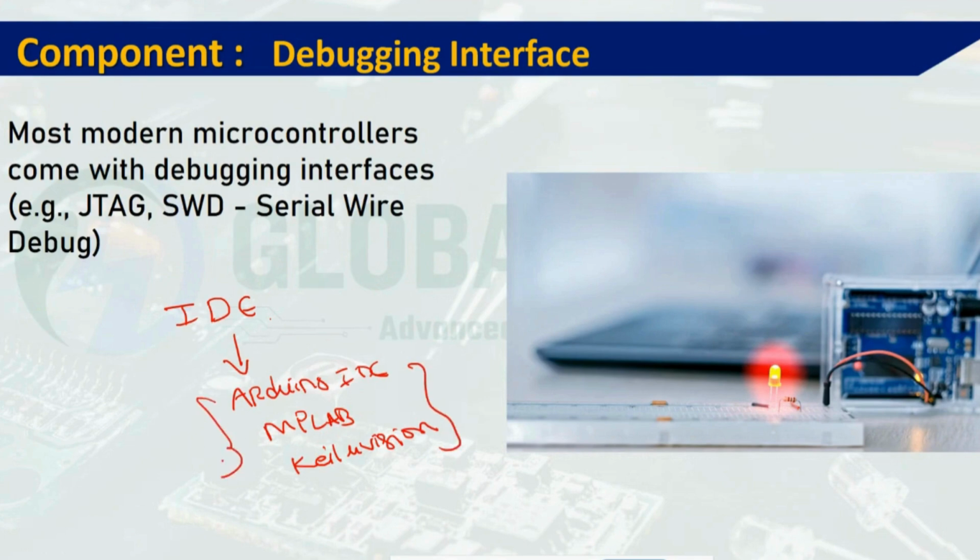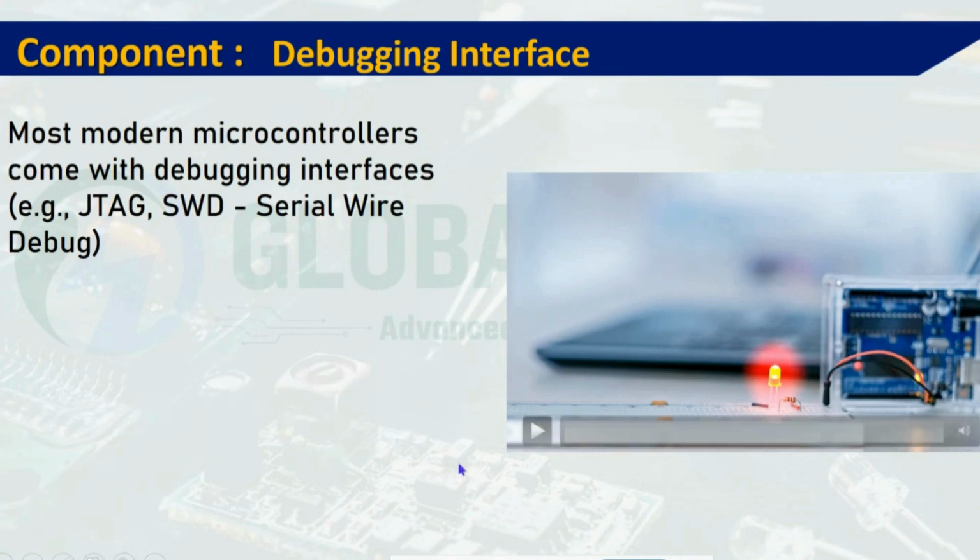In this, we are able to write our program, and we are dumping it into our hardware. The dumping here is the flashing. So flashing or sending the code, whatever we have written, we are dumping or debugging or flashing, which can be done via some of the tools using JTAG and serial wire debug tools. And to flash our code efficiently, we need the bootloader.